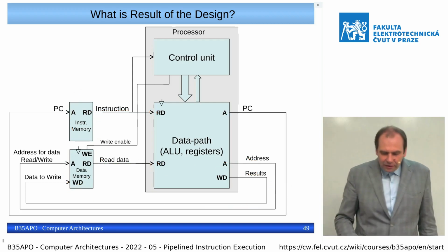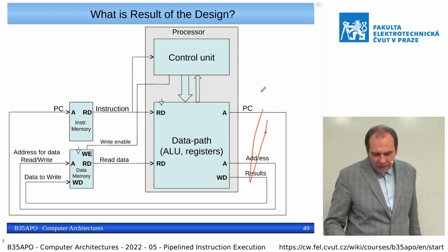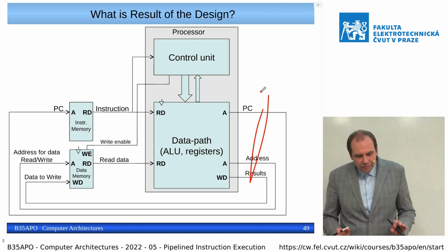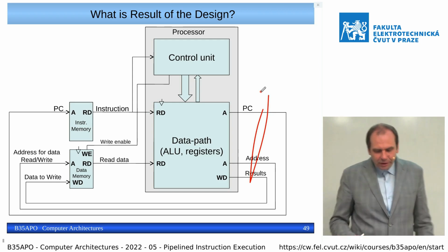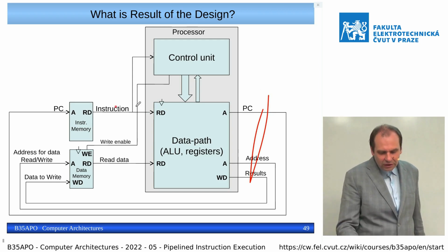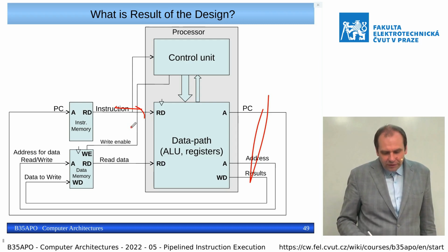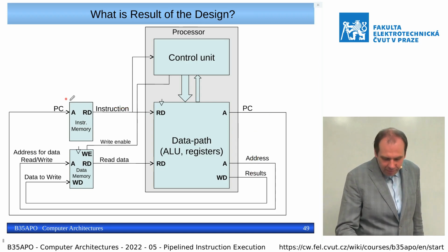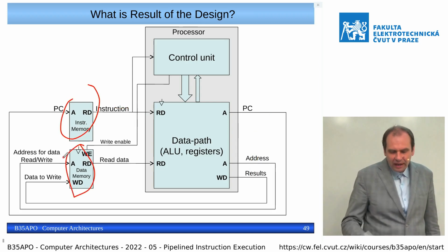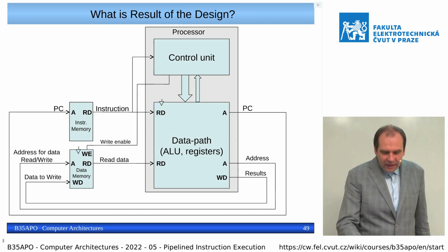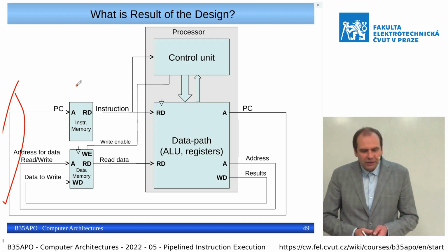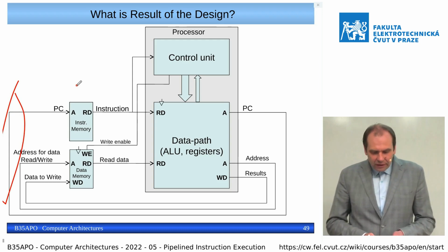We can even combine those two buses together with some logic which stalls the CPU if it wants to read the instruction together with the write or read of the data. But we usually have a separate cache for the instruction and data, so the actual design looks more like this Harvard, and then there is a unification on the second level of the cache, so it is quite often quite well matching.